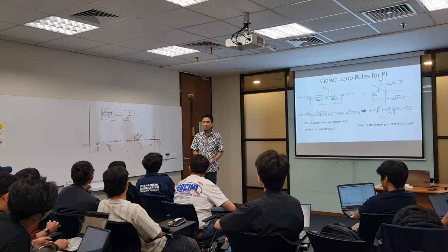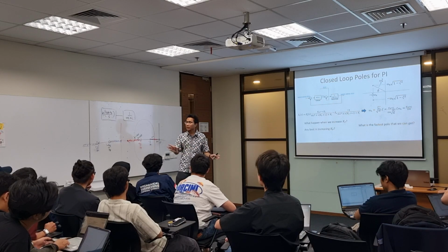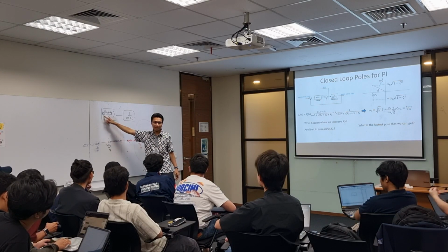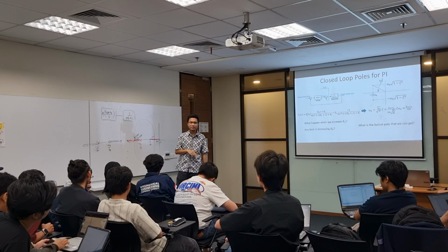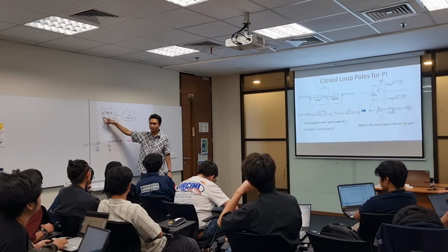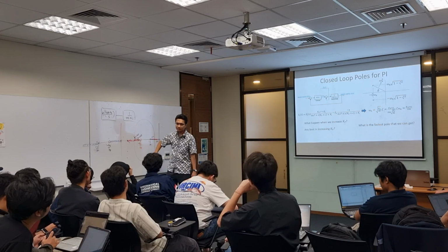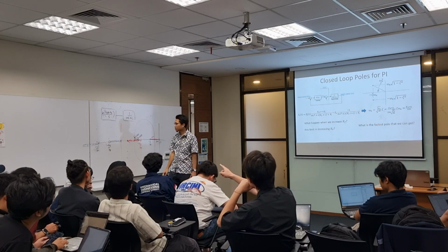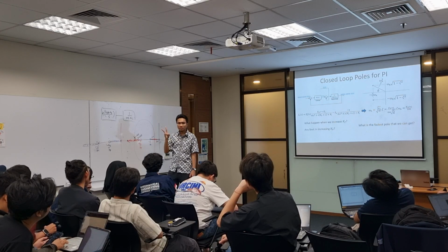So my drawing here is the collection of all closed loop poles if I vary the k in here from 0 to infinity. Because we can adjust the k from 0 to infinity, I will get all of these lines. K equal to 100, then one of them in here, one of them in there, a double pole.